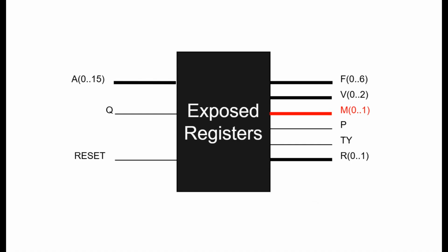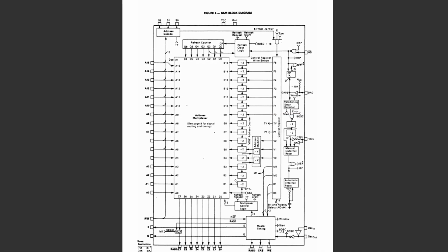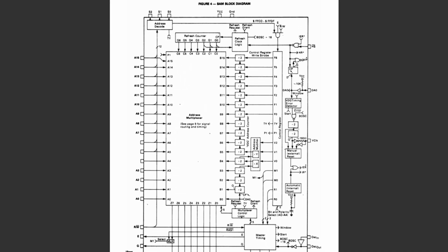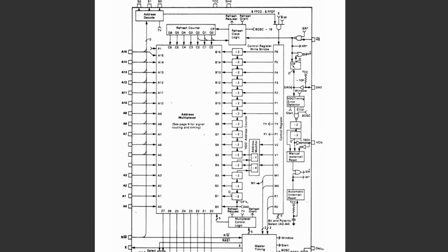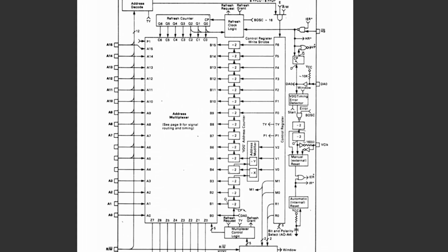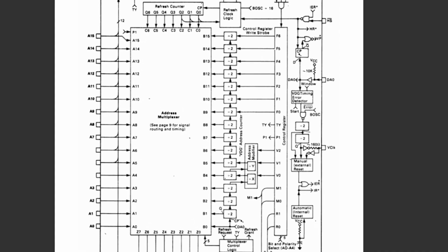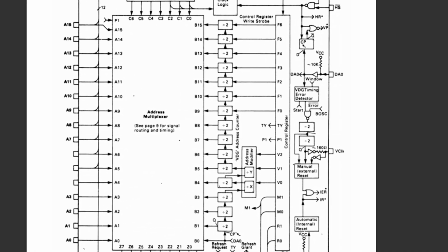The SAM also maintains an internal 15-bit video address register, B, that cannot be directly accessed. The base address register defines the starting address for each video frame at a resolution of 512 bytes, which together gives access to the entire 64K address space, but the exact value of the address register is hidden. It increments every time DA0 transitions from high to low. Effectively, DA0 is the least significant bit of the register, extending it to 16 bits.